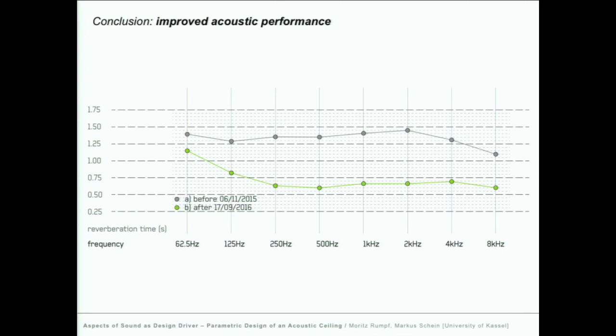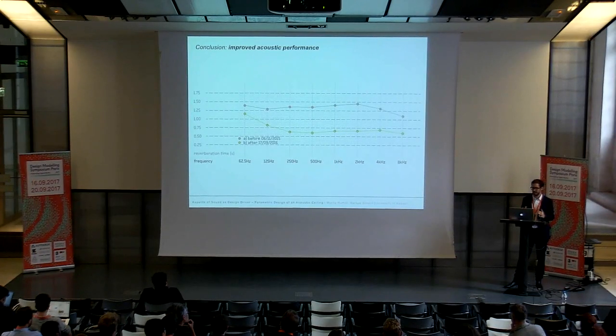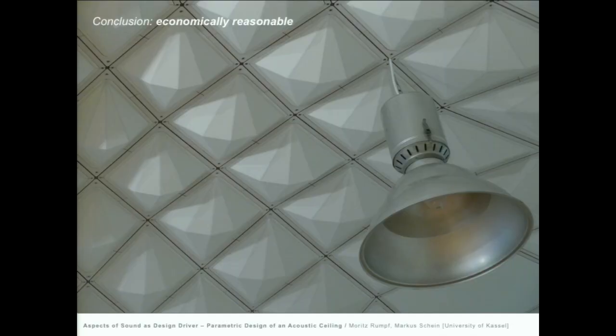To contextualize this, the general recommendation for good audibility and comfort in equivalent spaces is 0.5 to 0.8 seconds. And we've heard that this also coincides with a subjective impression of very content users. Also, despite the overall size and amount of non-standard parts, the structure was still economically reasonable. And as a case study for the implementation of acoustic simulations, we learned a lot.